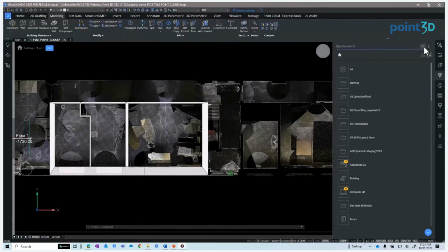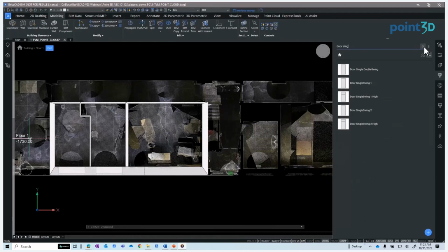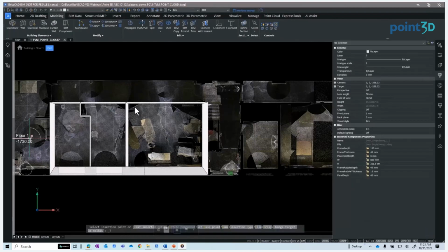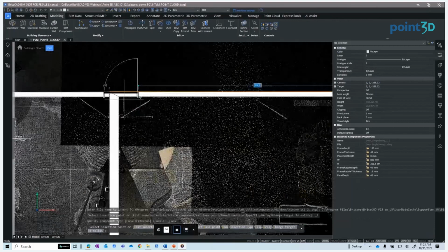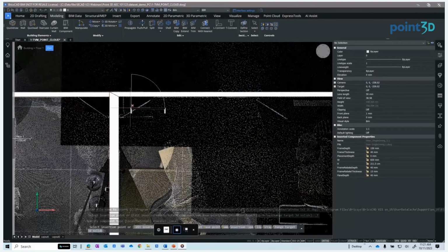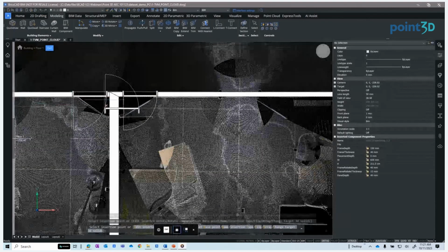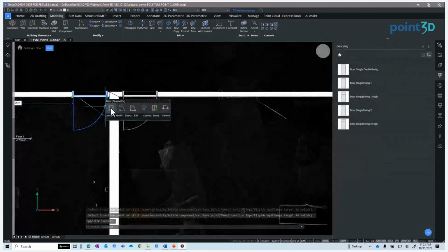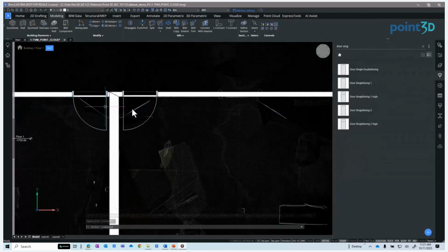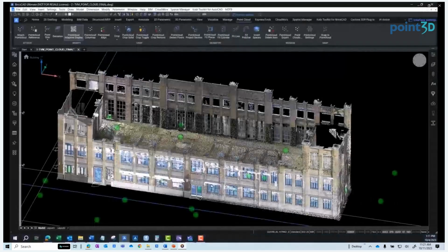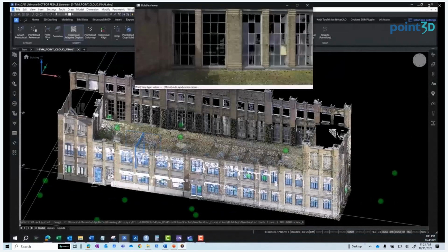Now popping back to top view mode puts us in plan view to insert the doors. Door blocks are also available in the library panel, and they're inserted much like the windows are, even though the model is oriented differently. Again, we'll use the point cloud as a reference guide to accurately place the doors. Moving the cursor along the wall reorients the door as it's inserted. Or insert the door and then flip the swing or flip the hinge of the door after it's been placed. Now here's a more complete version of this model with all the walls, doors, and windows.